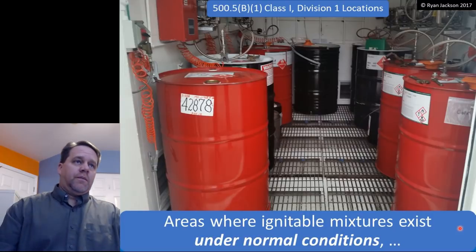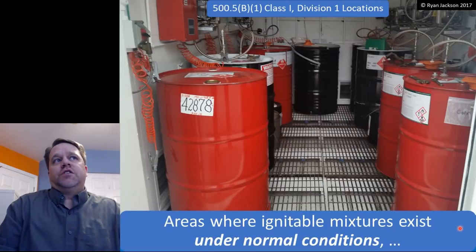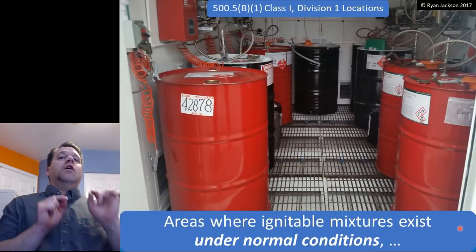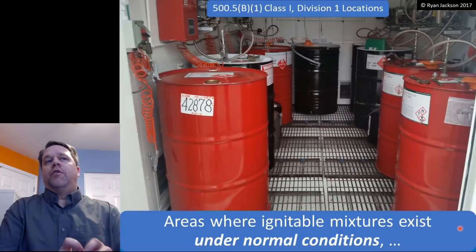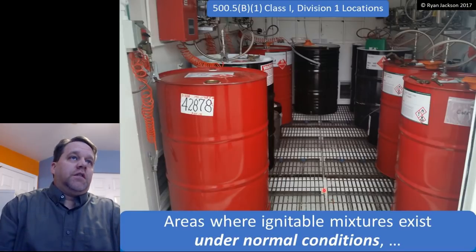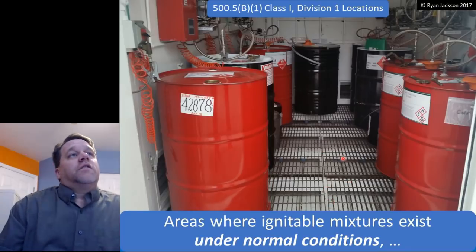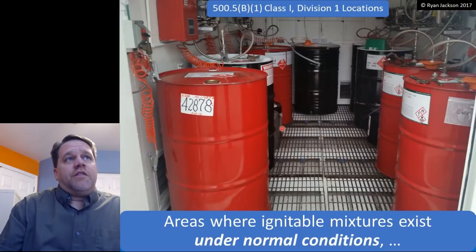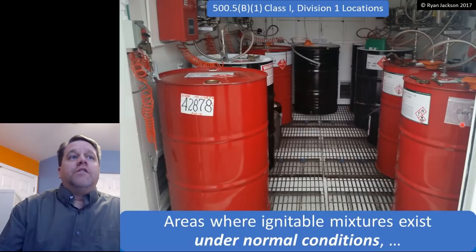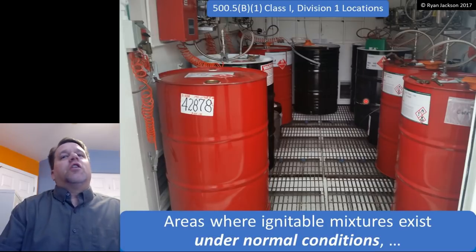A Class 1 Division 1 location is an area where ignitable mixtures exist, and here's the key, under normal operating conditions. What's the normal condition in this room? If I walk into this room, there is the hazard, there is an ignitable mixture. The normal condition is that in here, these barrels are open and closed all the time.